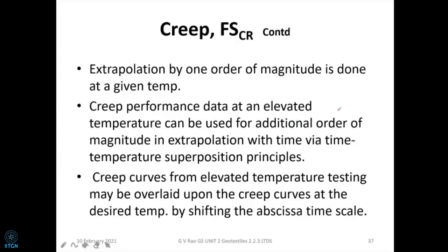What we know already is that if we are working in Kanyakumari, the ambient temperature is going to be high. If you are going to Kashmir, the ambient temperature is going to be low. And we know that at low temperatures the creep is going to be less, and at high temperatures the creep is going to be more. So using the same thing, we are going to conduct tests at artificially higher temperatures than what is prescribed in the design. That is the elevated temperature we are going to use.